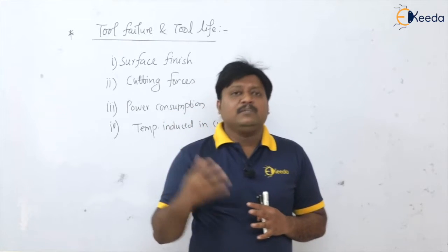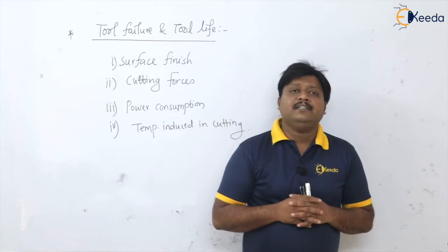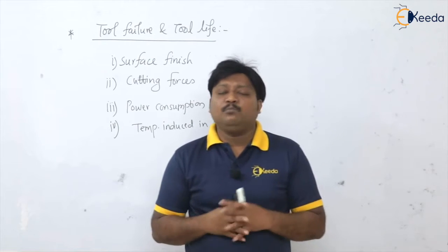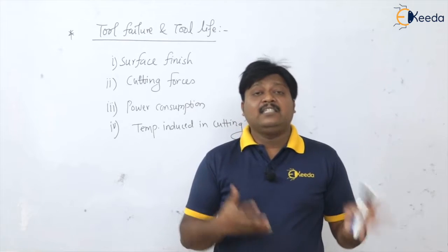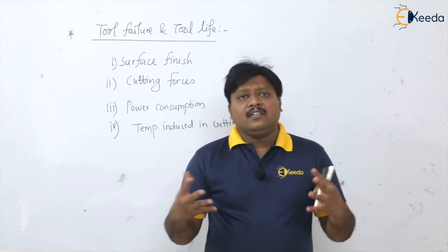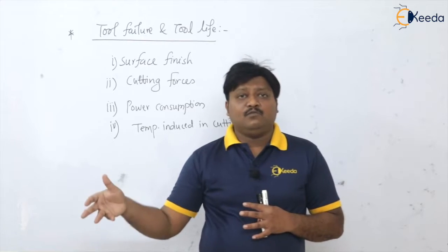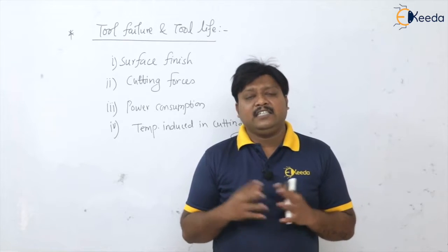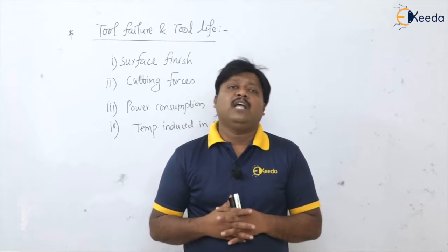And during the machining, if you measure the value of the cutting forces induced in the cutting operation, and you observe that the values that you are getting by this dynamometer are more than 15% of the actual values that we have calculated, then you can say that yes, the cutting forces have gone beyond the limit and the tool has failed.